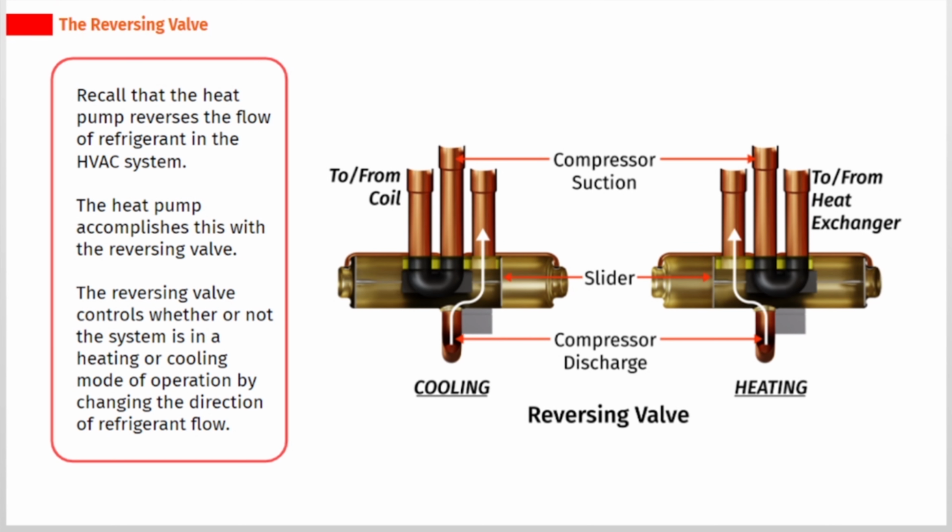Recall that the heat pump reverses the flow of refrigerant in the HVAC system. The heat pump accomplishes this with the reversing valve. The reversing valve controls whether the system is in a heating or cooling mode of operation by changing the direction of refrigerant flow.